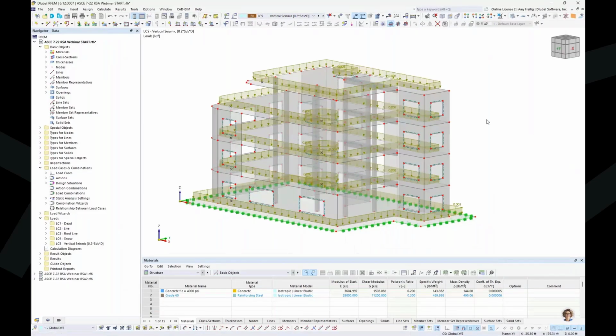So you can certainly use the base program alone, RFEM 6, to apply any seismic loads as a static load type if you prefer. But now we want to move into the horizontal or orthogonal seismic loads. And this is where we want to activate now those particular add-ons.